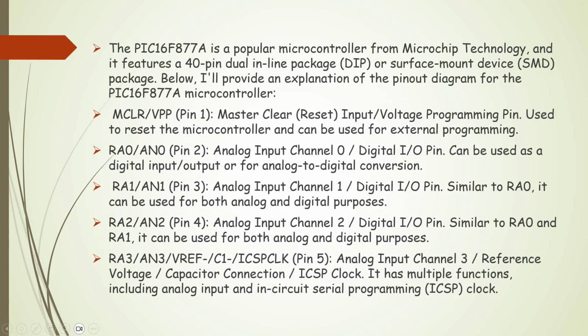It's a popular microcontroller from Microchip Technology with a 40 pin dual in line package, and a surface mount devices package. Below, I will provide an explanation of the pin out diagram for the PIC 16F877A microcontroller. Pin 1 is the master clear or reset pin, an input pin with a voltage programming function, used to reset the microcontroller and for external programming. Pin 2 is analog input channel 0, which can also be used as a digital input for analog to digital conversion.